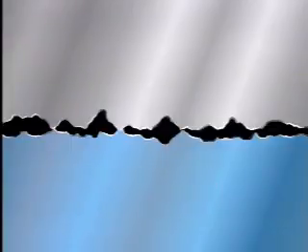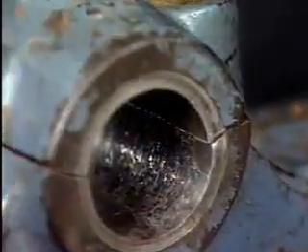Friction is also produced while the equipment is running, as the jagged surfaces and any small metal pieces that break off the surfaces scrape against each other. Microscopic scratches left from this scraping can eventually add up to severe wear. The purpose of lubricants is to make two surfaces slide against each other more smoothly, so a lubricant is a substance used to reduce friction. The lubricant separates the two surfaces and reduces the amount of contact between them.